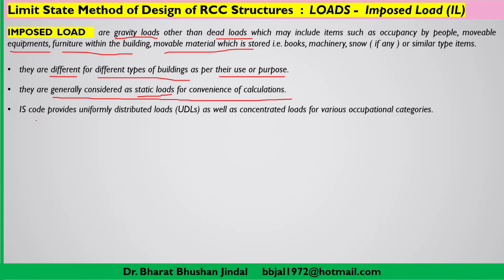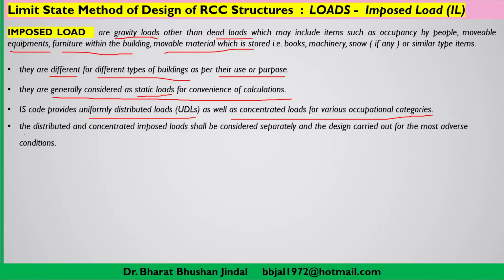The Indian Standard Code provides uniformly distributed loads as well as concentrated loads for various occupational categories. So you can refer to the Indian Standard Codes for various categories of loads. The distributed and concentrated imposed load shall be considered separately, and the design carried out for the most adverse conditions.